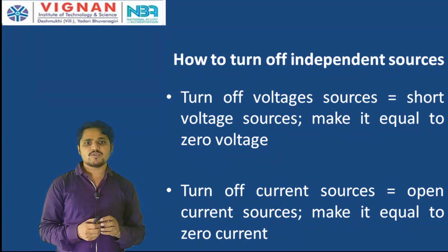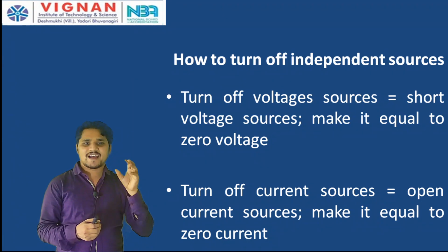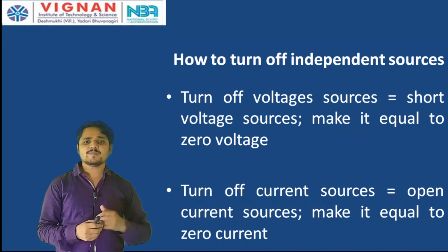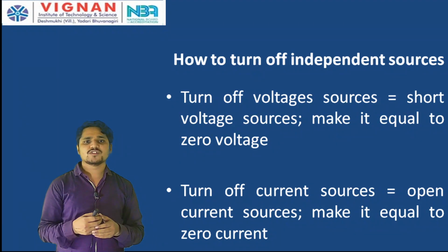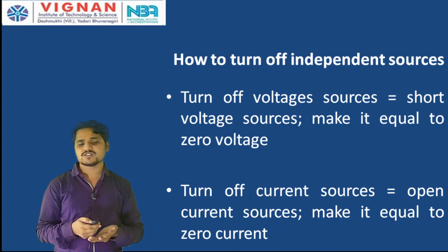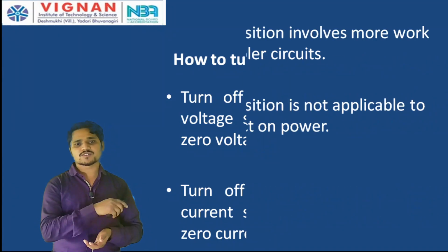In the first step, we assume that only the voltage source is acting and we kill the current source, that is, replace it with an open circuit. In the next step, we kill the voltage source and only the current source acts. Then you find the responses, and at the last step you add the responses. It will give you the total response.